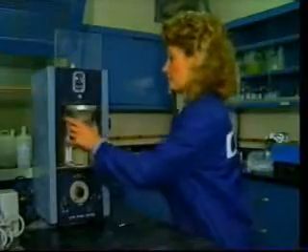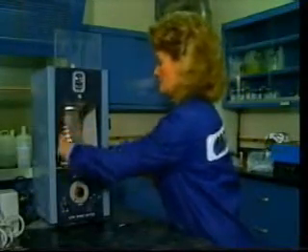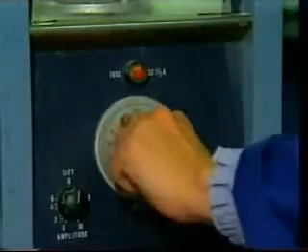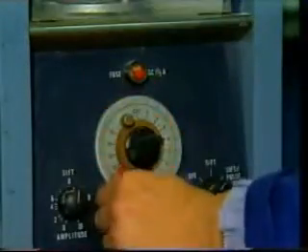The slots, cut into a metal liner, must be small enough so that the formation sand does not pass through without quickly bridging off. Slot width is usually based on the formation sand sieve analysis. Generally, a slot width is sized so that 10% of the formation sand will not fit through the slot. The intent is that the other 90% of the sand will bridge off. A slot of this size has a designation of D sub 10.